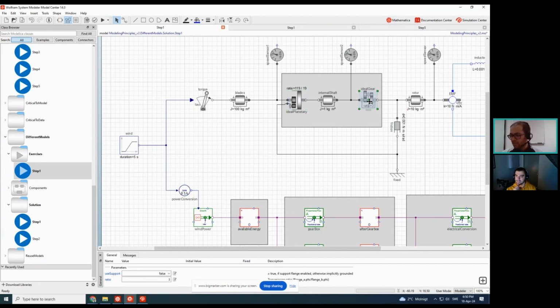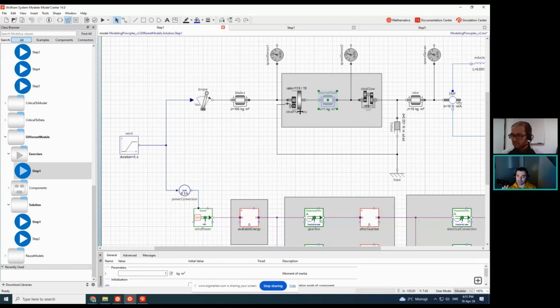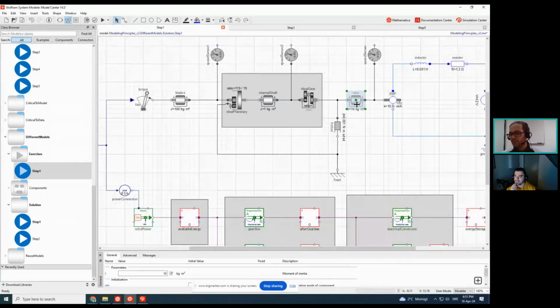So we have an internal shaft inertia to represent their momentum. In a way we lumped the whole gearbox into that internal shaft component in terms of the inertia part. Okay, right. And then once we have the gearbox, similar to the blades, we come to the rotor side of the motor, and we represent that inertia with the same element, right?